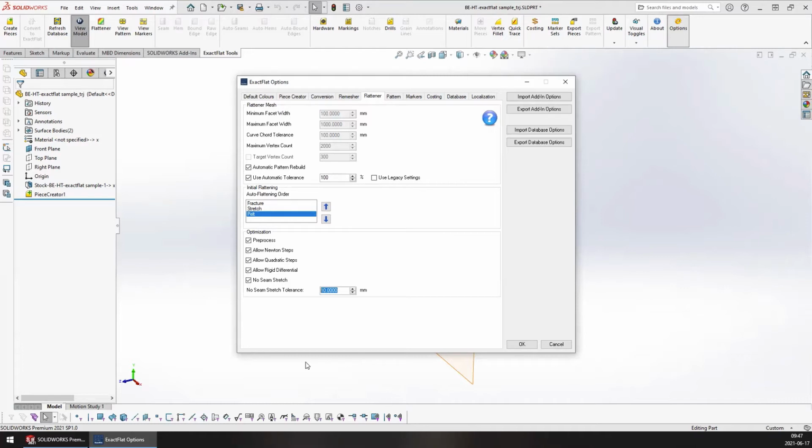So make small adjustments. If you notice that you're starting to get edge deformation, then back off, raise the tolerances a bit. And if you're still finding that you have too much deviation, that's a good indication that you may need to introduce a cut into your part, or even a dart or a relief cut. Probably the best thing to do would be to split your pattern piece in half and try again, because there's probably a certain geometric feature in there that's just introducing too much strain.